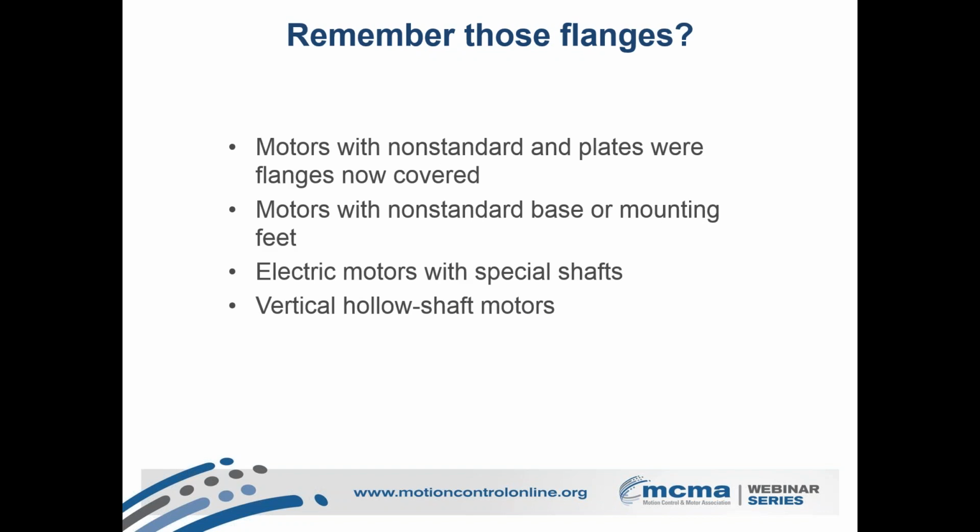And the key thing here is, remember we were talking earlier about people trying to dodge the regulation by doing a little bit of cute customization and stuff. That doesn't work anymore. Now, even if you've got non-standard plates and flanges, you've got unusual base or mounting feet, special shaft, even things like vertical or hollow shaft motors, a whole bunch of stuff that you would have thought would have been exempt in the previous rules. That's not going on anymore.